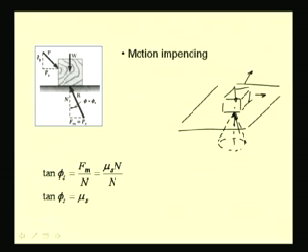But when the frictional force reaches this limiting value, that is Fm, then the resultant lies on this cone, which we call the cone of friction, then we say that the motion is impending. So, this kind of an analysis is sometimes useful in certain class of problems.